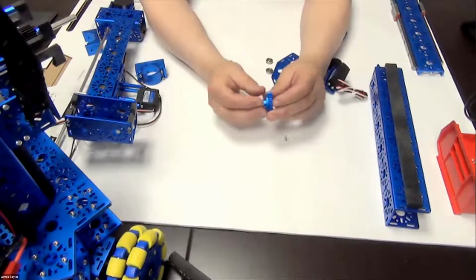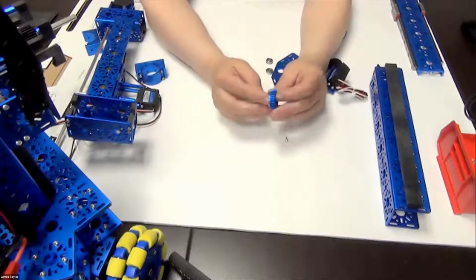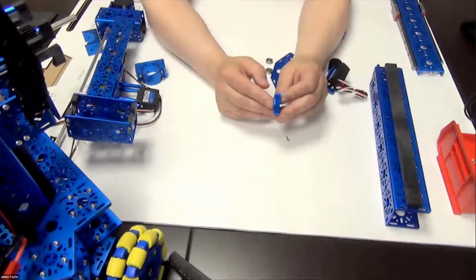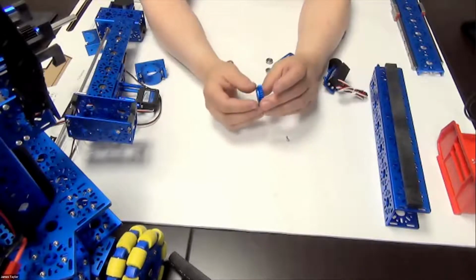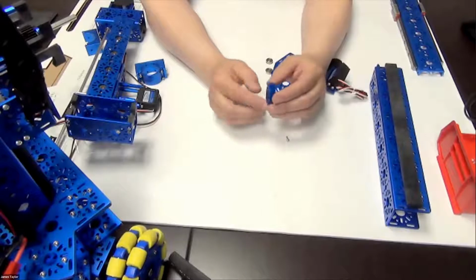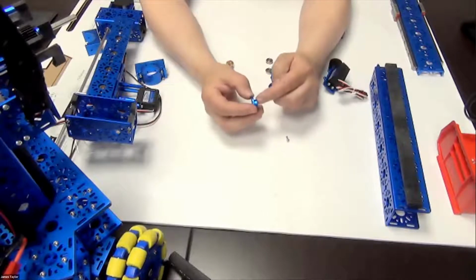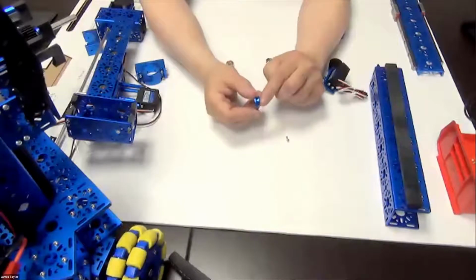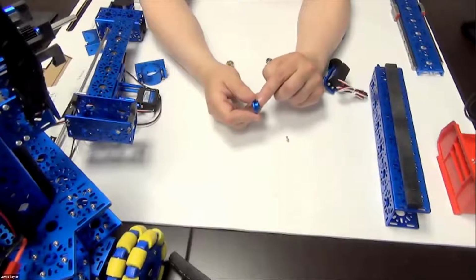You can do it this way, or you can try to do it this way. Just remember that if you try to do it this way on a gear, you don't have access to that set screw that's on the inside of it. There are 2 set screws on a shaft hub, one for the flat and one for the other side. So just be wary of that design.